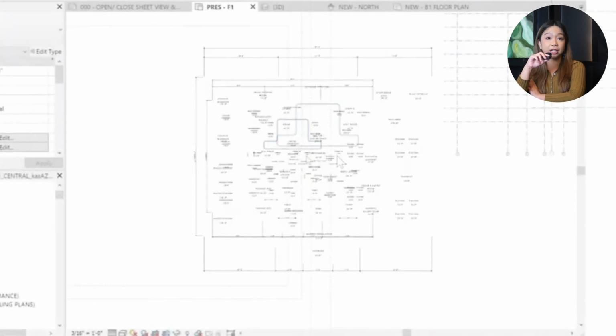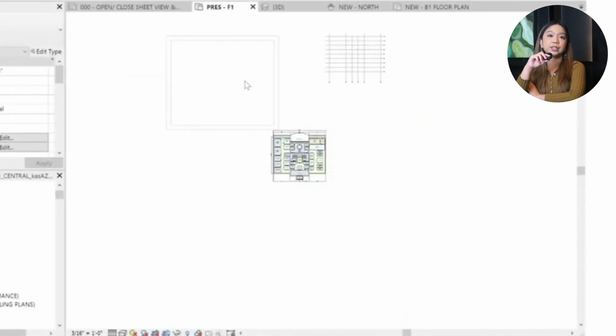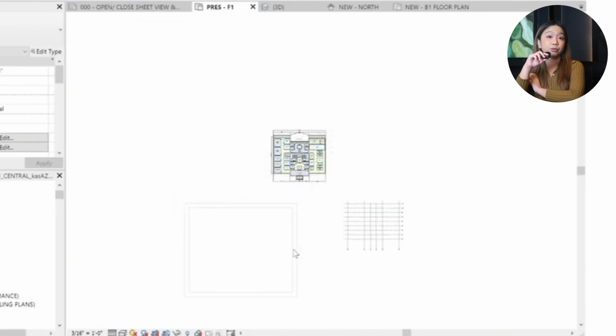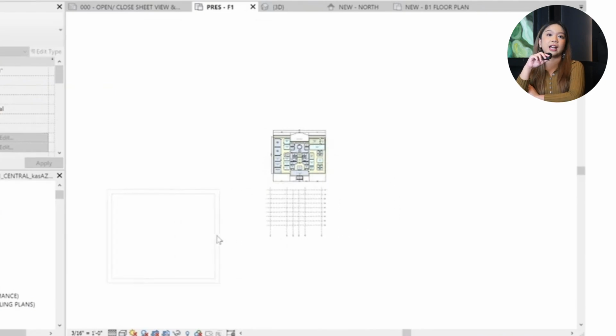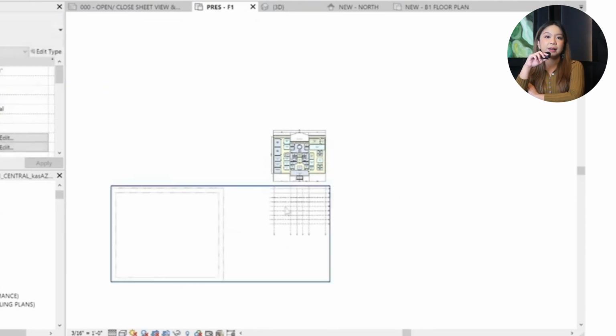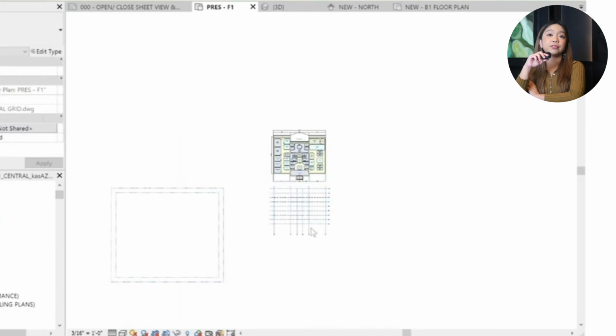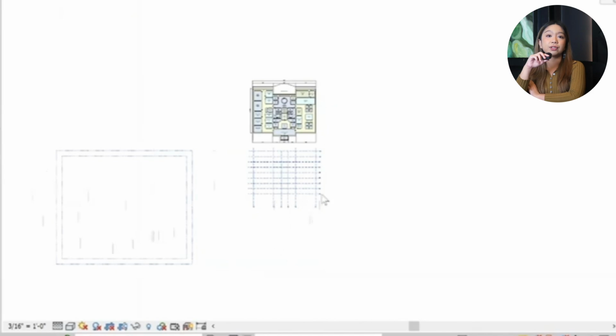The CAD file will appear, hovering in your view. At this stage, it's essential to note that Revit treats the CAD file as a linked reference, much like an external reference, XREF in AutoCAD. You can snap to points and measure off the CAD file, but it remains a separate entity, ensuring your Revit model stays clean and manageable.